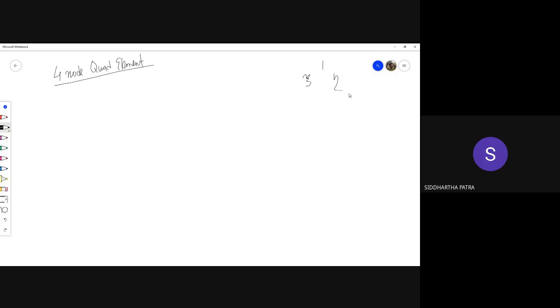The shape function of the CST element has either 1, xi, or eta, and this is what constitutes the shape functions of a CST element. Hence, the CST element is called a linear element. It is linear in xi and eta.